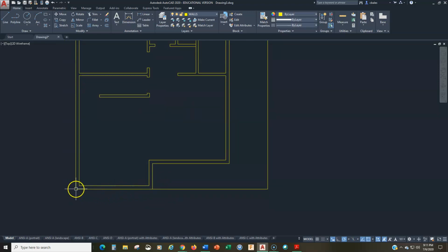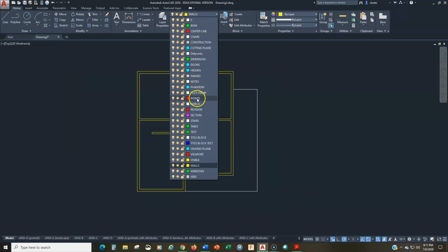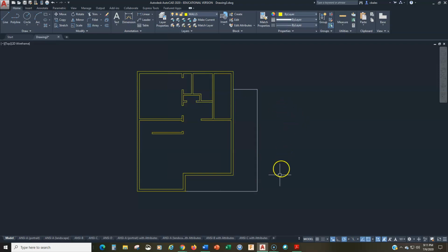The wall clearly continues. We have an exterior wall here that turns into a porch line, the line on the drawing for the porch, but I need them on 2 different layers, and they're going to plot with different line weights. So what I'm going to do is I'm going to trim this back, and I'm going to draw another line here. Right? That way, when I select these lines right there and put them on the porch layer, it's correct. Okay?